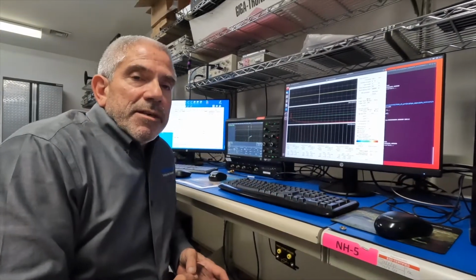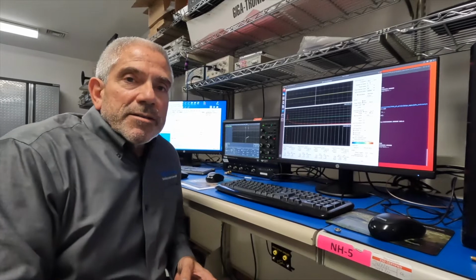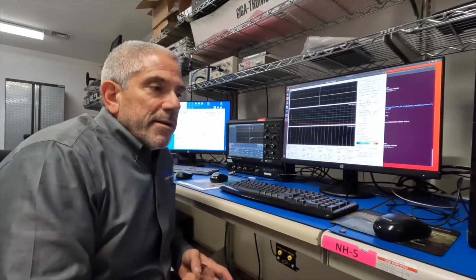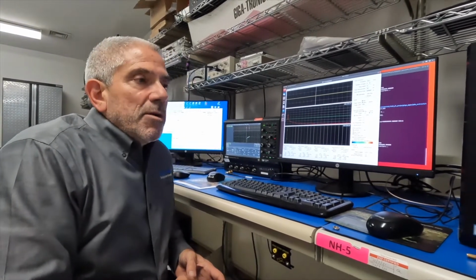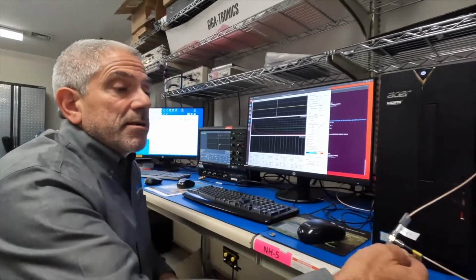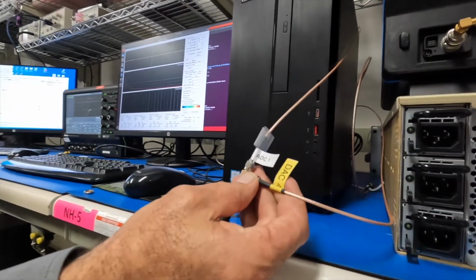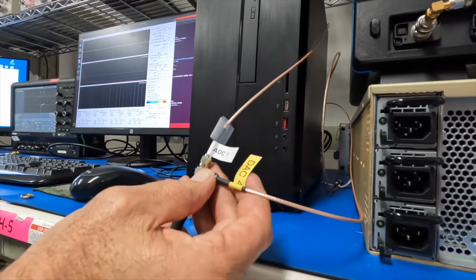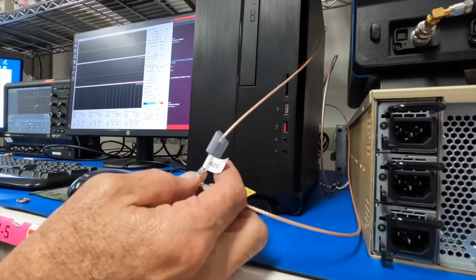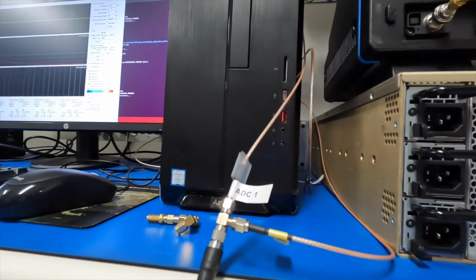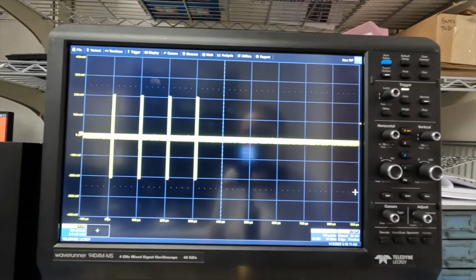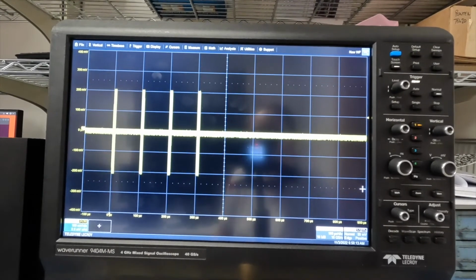So now that you've seen what the 8-channel RF system on a chip card looks like, including its 8 channels of digital to analog conversion and its 8 channels of analog to digital conversion, we're going to be using one of the DAC outputs, DAC channel 4, to feed a waveform into A to D channel 1. And we're going to be using that FPGA and all the ARM processors on board to analyze the pulses and give you the pulse parameters in real time.